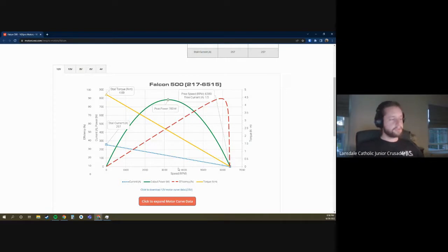So you'll see when the motor is going about half speed is where its peak power output is. And power is a limiting factor in robots and many other systems as well, so we're usually trying to maximize this power output. So when you spec motors, when you're determining which motors and which gear ratios to use, you want to try to size your motor so that it runs at this peak power range.